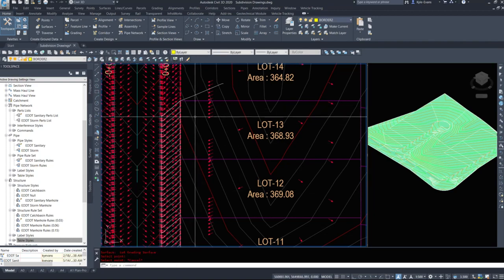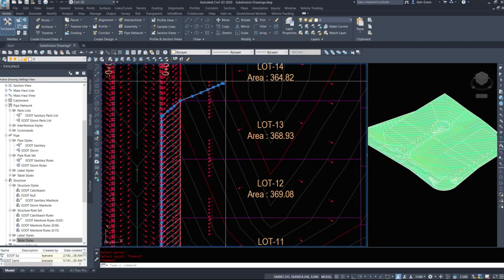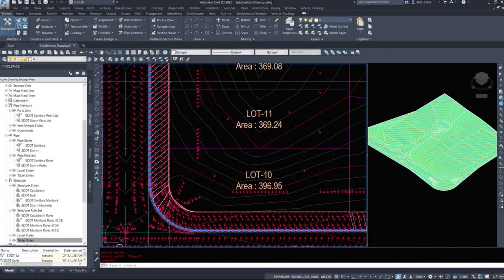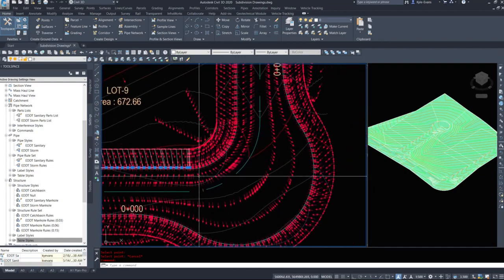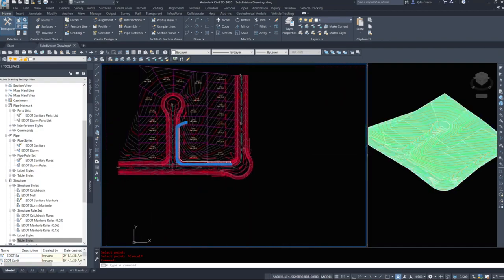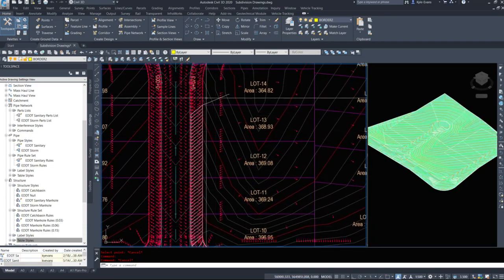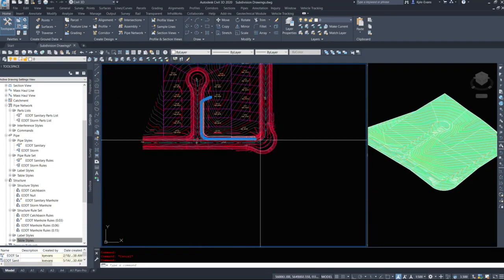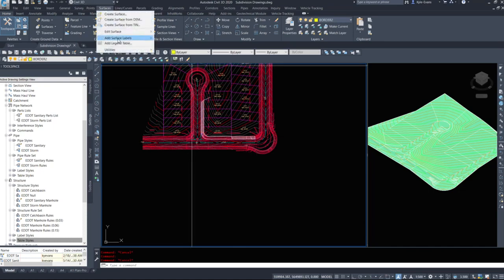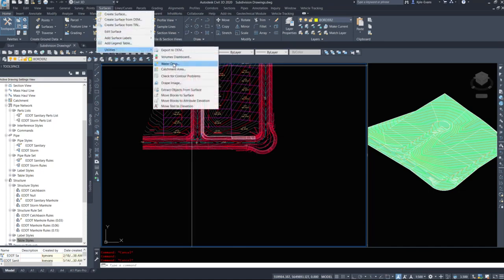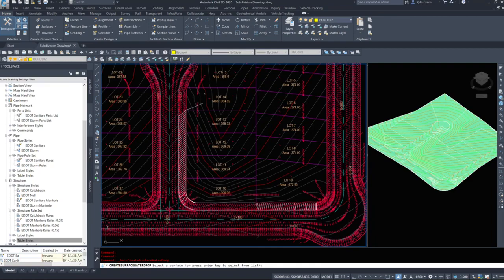And escape doesn't work for me. Oh, there it does. So I'm going to click on this polyline, 3D polyline. It's going to show me that water is flowing down the corner, around, and is stopping in this location. Yes, I know I have a whole bunch of other points that came with that first one, but overall it's going from here down to here. So I'm going to run the water drop again, and hopefully I can hit escape after this.